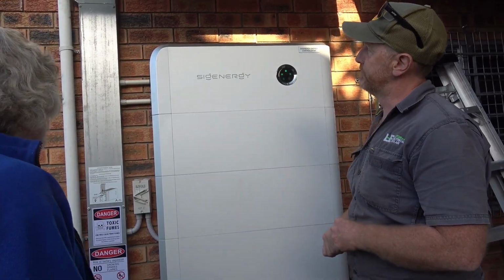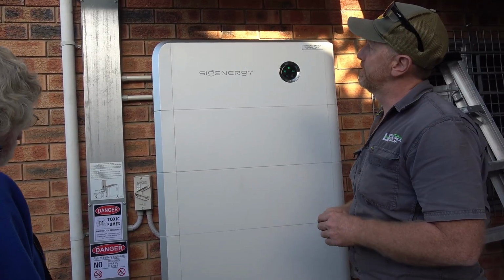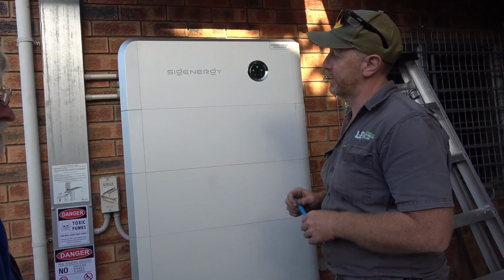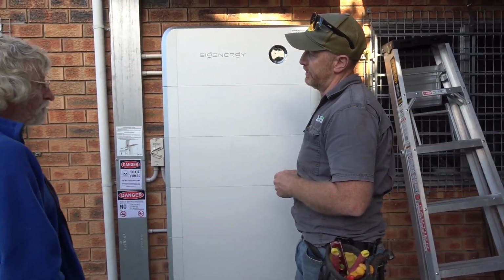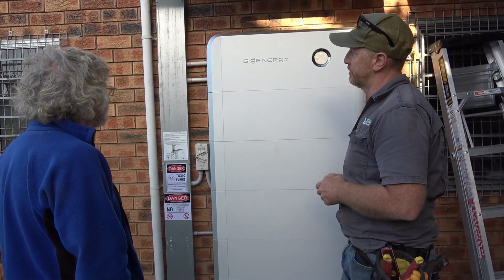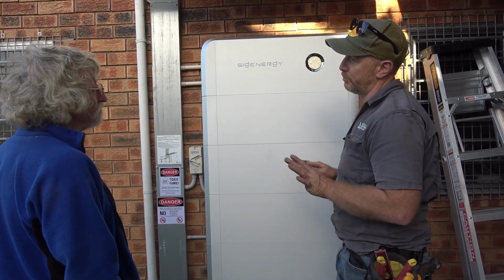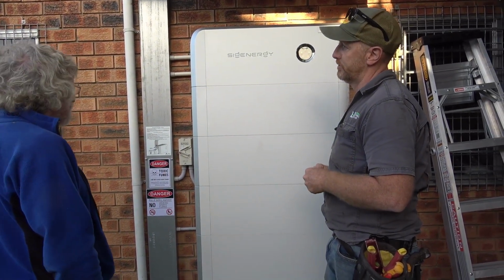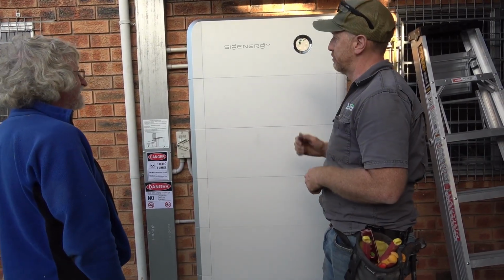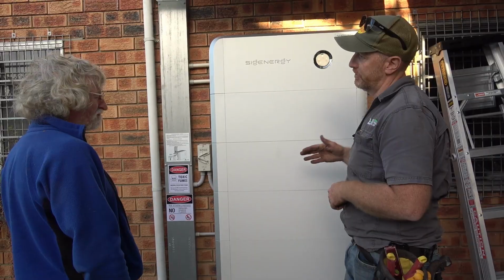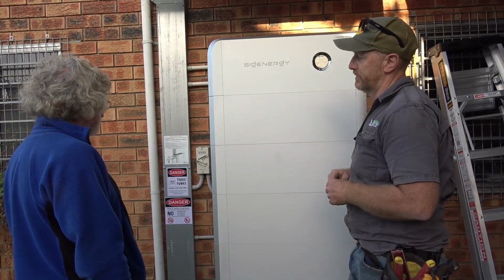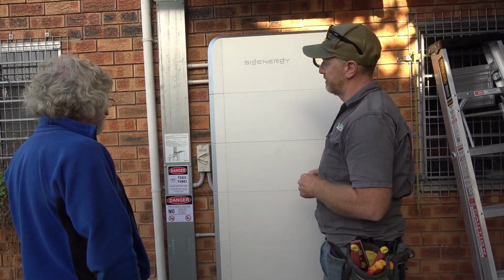And then because your panels are basically flat, I'd recommend cleaning them once every 6 months or so. You can do it yourself or get someone to do it, but no chemicals, just water. Just water. Hose and broom. Hose and a squeegee. Perfect. They don't have to be spotless, but you don't want a layer of dust on them either. Dust and leaves and whatever. Leaves, yeah. Just blow them down, and then maybe once every 6 months.